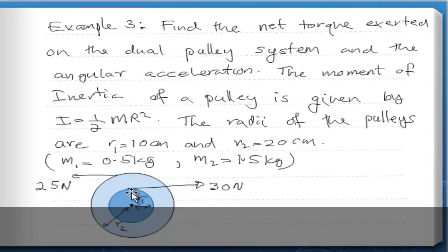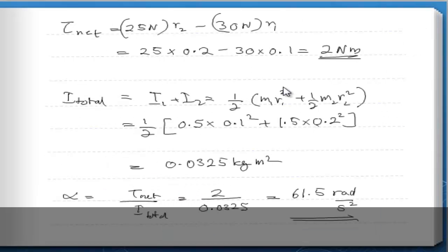But in this situation, the radius is the lever arm because this force is always perpendicular to a line joining the point the force is exerted on the rod with the center. Normally for a pulley, the torque is radius times the force. So we use that here.